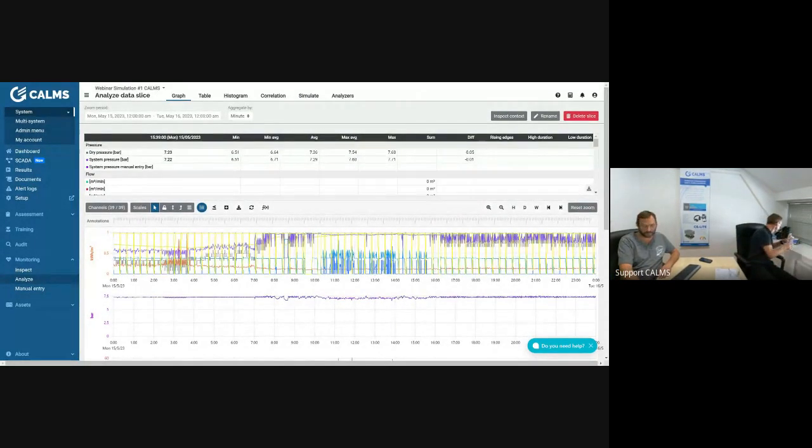The steps that you do before you start the simulations will guide you into which simulations make more sense. One of the simulations that makes sense some of the time, not all of the time, is to replace one existing compressor with another compressor in the hope that this will improve the specific power and therefore the energy used by the compressor station. So today we will do that.